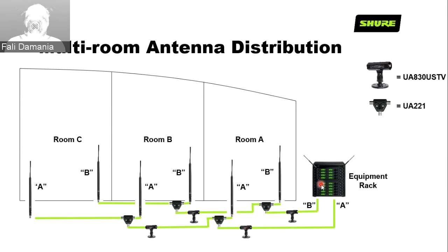And again, remember, just like the distributor or any of the higher model digital RF devices, you can chain up. It gives you enough power to turn on 2 of these inline amplifiers. If now you had a 4th room and you need to add 1 more amplifier, that's when over here you would place a bias T. So in this example, it's pretty straightforward, but you're considering that you're not doing more than 2 levels of combination, which we'll actually see what happens when we move to a 4-room system.